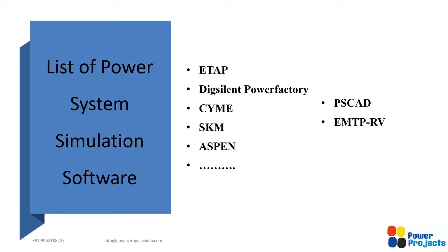One software will not fit all the requirements. So it is very important to select which software to use for which studies. For example, if you select PSCAD or EMTP-RV for a load flow analysis, yes, those softwares can do it, but is it really worth investing that much time and effort just to perform a load flow? No. So we will talk about that perspective: what is used for a steady state analysis, why that software is better for steady state analysis, and in what case you have to go for other simulation softwares, which we will discuss tomorrow.